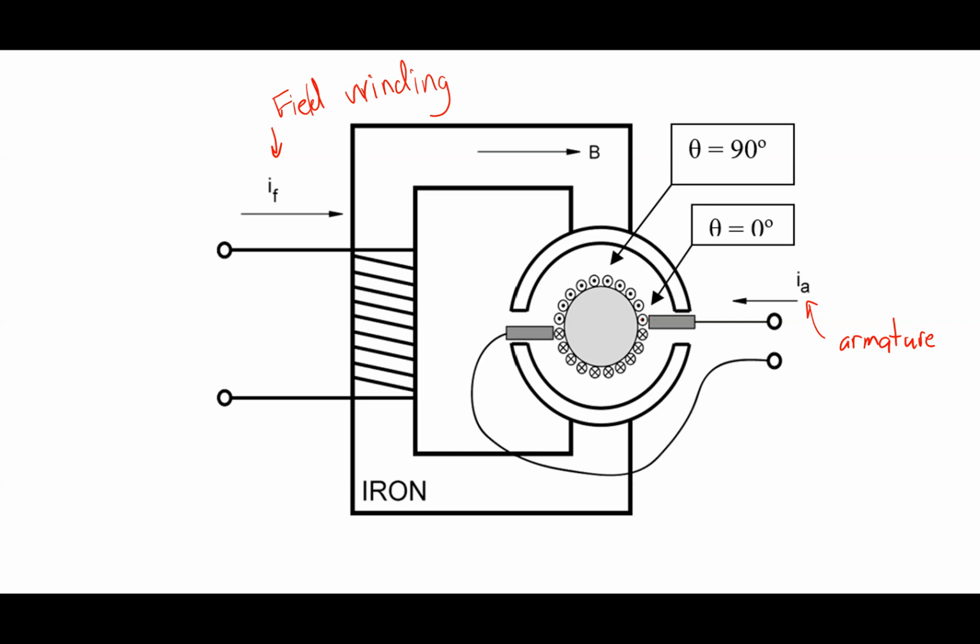These guys here are iron sheets again. And I see I've got all this sort of orange stuff here. What's all the orange stuff? Windings. That's my copper, right? So basically I got windings all around this guy. Those are the windings that I have on this rotor, okay? So here, I have all these windings on the rotor. Now, there's a very special way that this guy is wound. But the other important thing about this is this, so see, I've got one side of this thing still here, right? I took the other side off to get the rotor out.